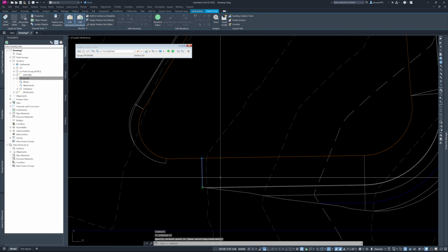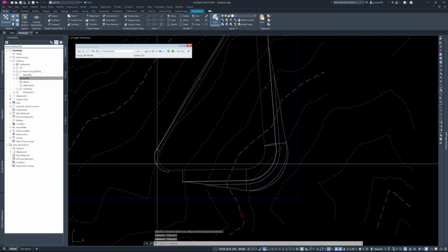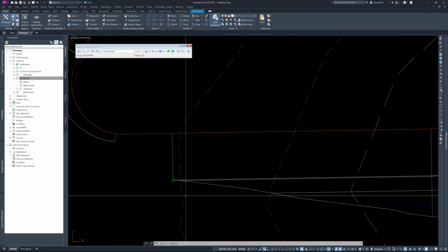And that should clean up our contours quite well. So this is a 1223 going this way, the 1223 going that way. Well, actually, we might need to pull this back quite a bit. Now that we look at this, because that right there is the 1222. Is that right? Yes. Okay. No, that's right, because we lowered the original feature line down to 1222.05. We should be real good right there.